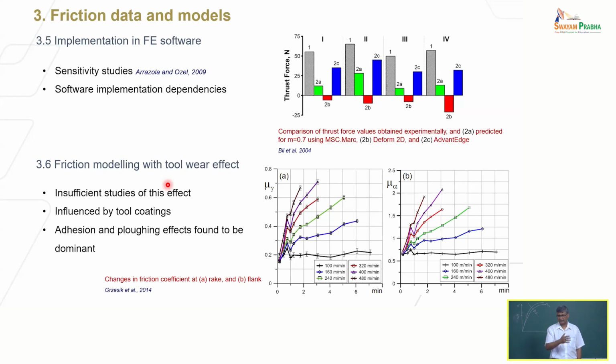And if you think about practice, when you use a cutting tool, you may use it to cut this material, then some other material, or even with one material you may be using a range of feeds and speeds, because if you plan a tool path in a milling operation, different features are being cut at different speeds, depths of cut, etc. So a simple description of tool life as a function of one speed is not enough, right? So it's not simple.